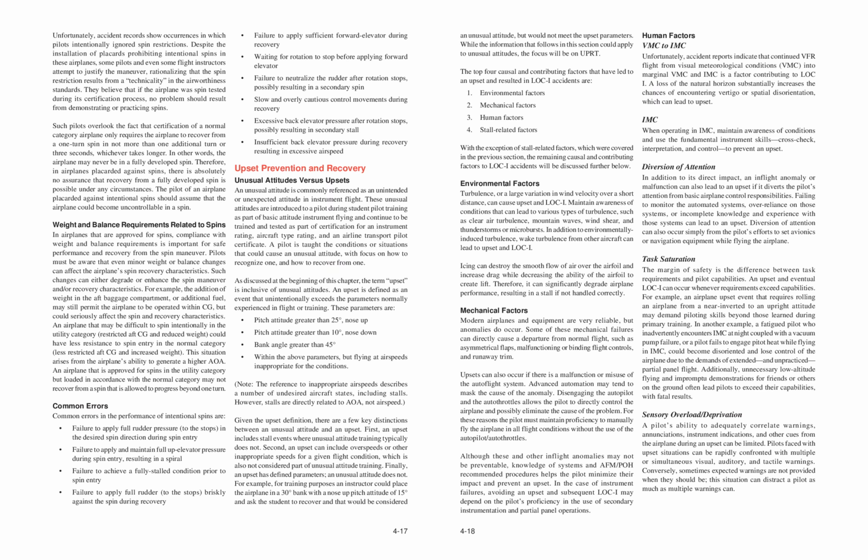In another example, a fatigued pilot who inadvertently encounters IMC at night coupled with a vacuum pump failure, or a pilot who fails to engage pitot heat while flying in IMC, could become disoriented and lose control of the airplane due to the demands of extended, and unpracticed, partial panel flight. Additionally, unnecessary low-altitude flying and impromptu demonstrations for friends or others on the ground often lead pilots to exceed their capabilities, with fatal results. Sensory overload/deprivation.